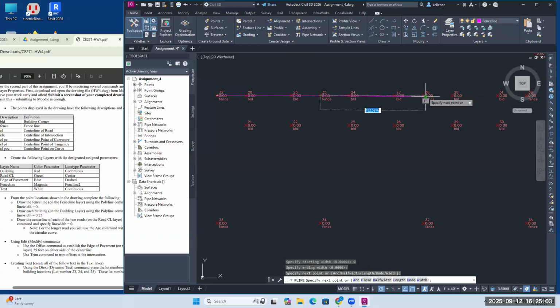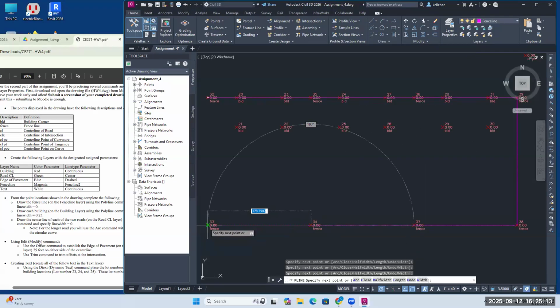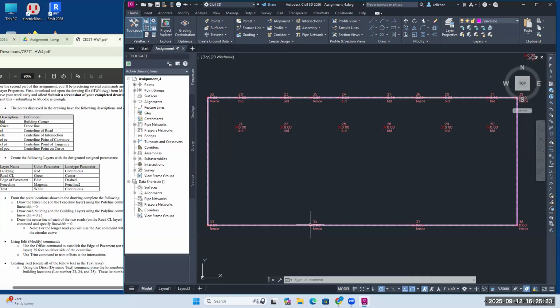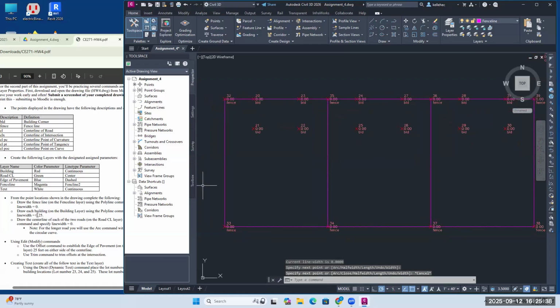And again, I can do this clicking. I can pan as I go. All right, over, I'm hitting all these lines. And then back up to the top and escape. If I want to repeat the same command, which I want to connect these fences because this is actually 3 lots here, I can click spacebar. And I can grab these P lines, escape, and spacebar, and P lines, and escape. So I've got a fence line.